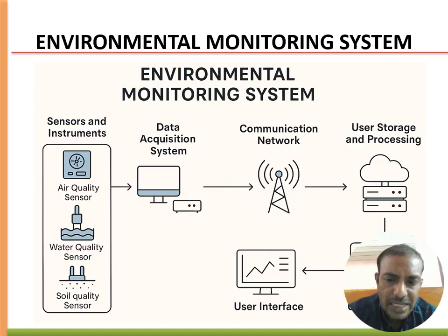And these are the things that are very much required as far as environmental monitoring is concerned. We collect the data by sensors in the environment. This data needs to be stored in a proper manner, and the user interface is used to extract the information at regular intervals, whether it is for leachate treatment. We have monitoring wells so that the data are regularly compiled and monitored at regular intervals. How this landfill is working, so as not to degrade the water quality and groundwater quality, and the same for different applications. So continuous monitoring of the data is very important. Dynamic analysis is also important as far as environmental monitoring is concerned.